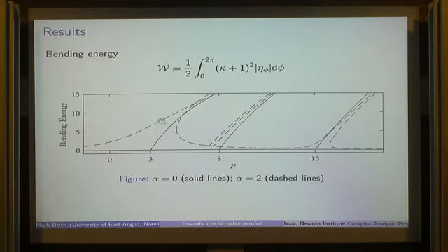So that branch there is the one that, let me see if I get this right, has its major axis aligned orthogonal to the flow. This branch here was aligned parallel with the flow. Okay? And a point of interest here is that the bifurcation point at 8 has moved out to bifurcate non-linearly from this broken branch. And those are the 2 mode 3 shapes coming off there: the one that was top-down symmetric and the one that's not top-down symmetric.